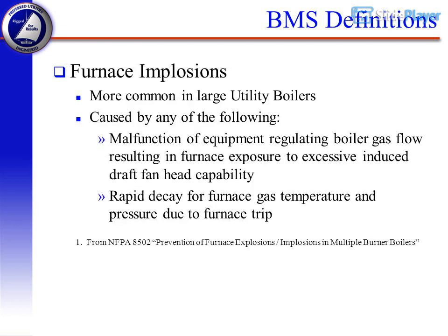BMS definitions: furnace implosions. More common in large utility boilers. Caused by any of the following: malfunction of equipment regulating boiler gas flow resulting in furnace exposure to excessive induced draft fan head capability. Rapid decay of furnace gas temperature and pressure due to furnace trip. From NFPA 8502 Prevention of furnace explosions, implosions in multiple burner boilers.